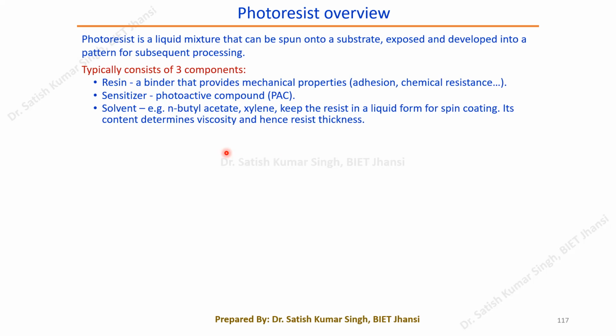It is generally 0.1 to 0.5 microns or 1 micron thick. It is not very thick; a very small thickness of photoresist is sufficient to do the photolithography operation.